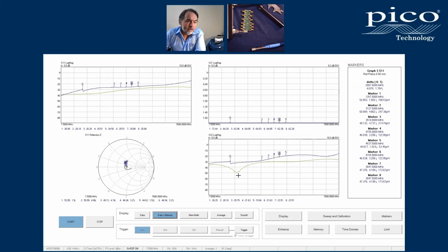Well, the explanation comes about because these two calibrations, this is the calibration resulting from using the line as our calibration standard. This is a calibration resulting from using the 50 ohm resistors, near 50 ohm resistors, the TRM match loads on our board, and this is a calibration using a known good, characterized 50 ohm in an ecal unit.